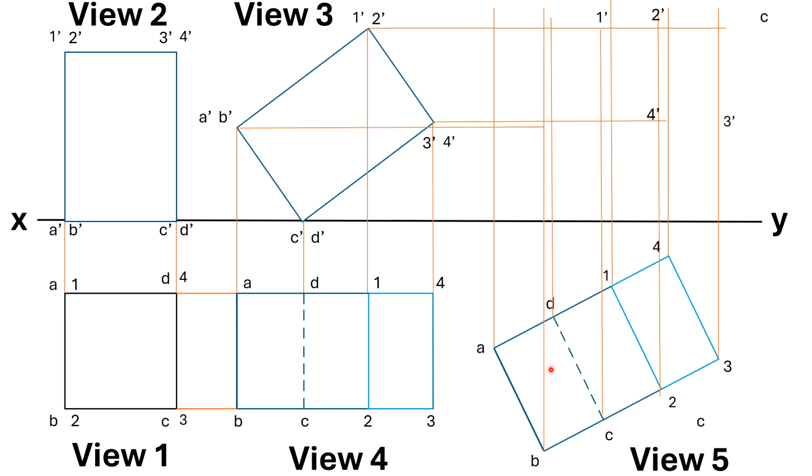Likewise 1, 2, 3 and ABCD also, if I project, the ABCD will come here. So A and A is getting projected here, this becomes a B, C and D. Now how to connect all these A, B, C, D and 1, 2, 3? If you carefully observe, I need to first draw an imaginary line in order to identify the hidden lines.